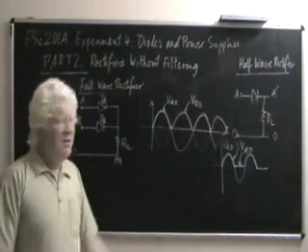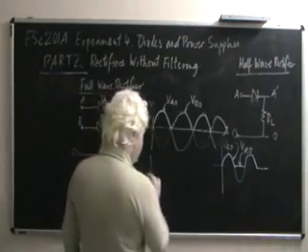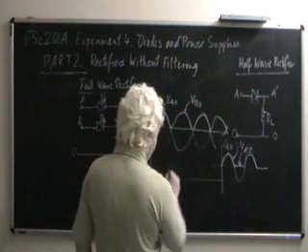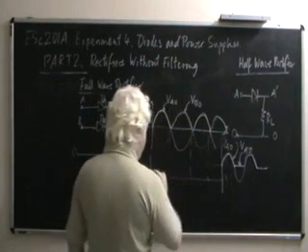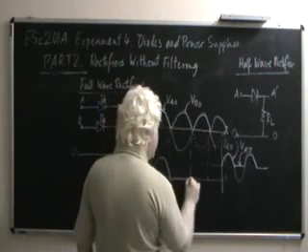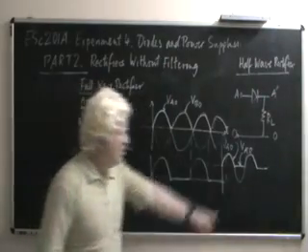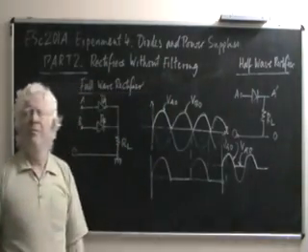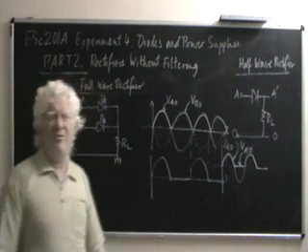So compare this with what the half wave rectifier gave us, which we will just draw below it. The half wave rectifier would just give you this and then idle over here. Again give you this and idle over here, as you see already in this graph. However, the full wave rectifier is busy on both half cycles.